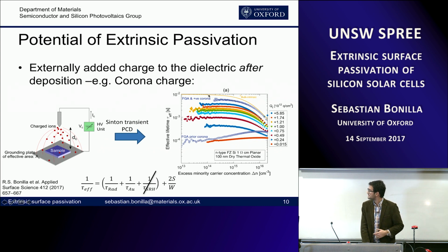Just for comparison, here is the intrinsic limit of that piece of silicon that we're using there. Here, most of you would have seen this split between different components of lifetime. In this case, we calculated the recombination velocity. For the case that doesn't have a forming gas anneal, this is equivalent to about 1.4 centimeter per second, which for those who are familiar with recombination metrics in terms of surface recombination velocity, is fairly good. And I'll later show how this compares to other work in the field.